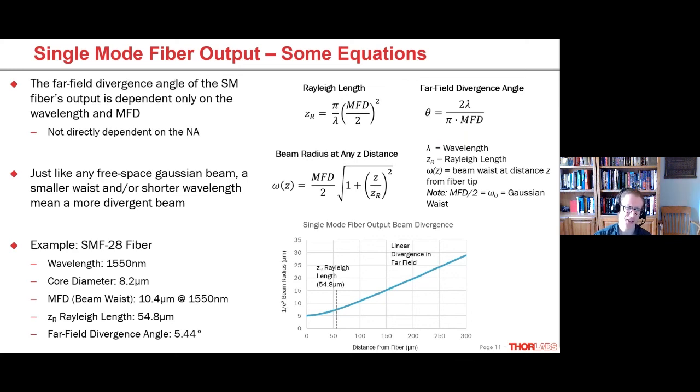The trade-off is that microscope lenses are typically only made to work with visible light. Things like the AR coatings on the lenses might not work in the IR, and maybe even the lens design, I'm not sure. So if you're thinking about a telecom fiber operating in the near IR, you would see microscope objectives used less, and things like aspheric lenses or a multi-element lens custom designed for the application are going to be pretty common.